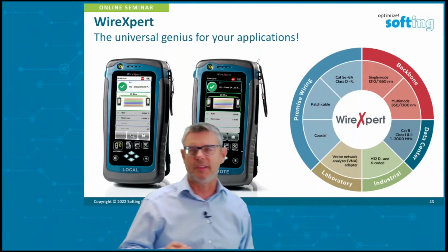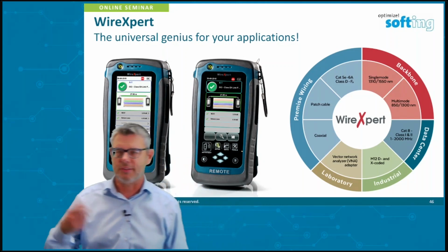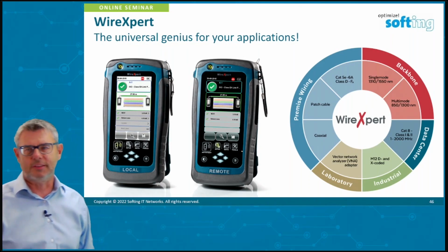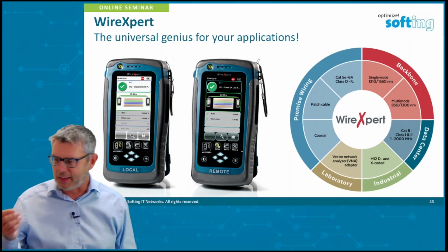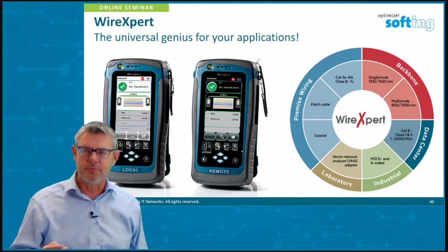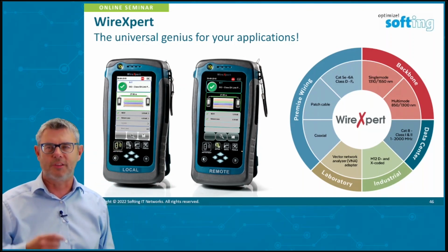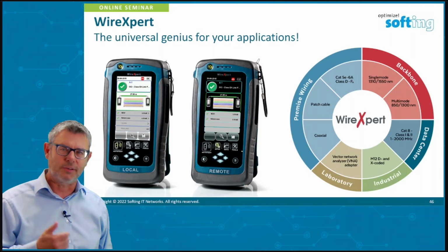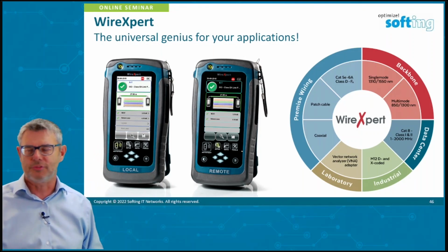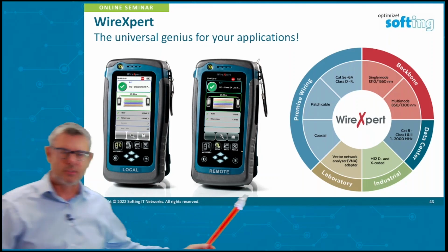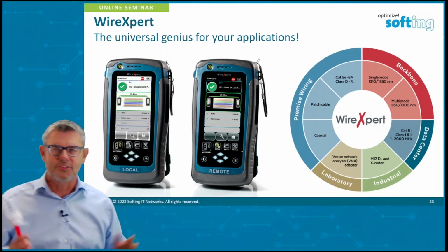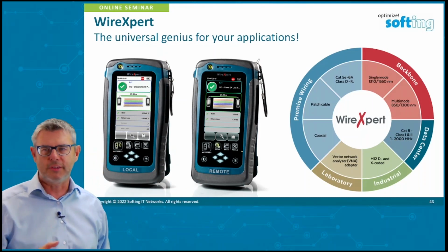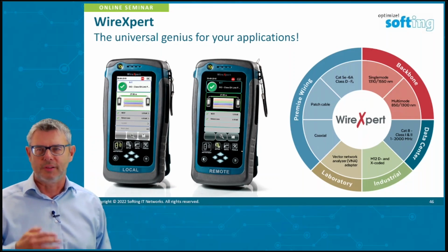With the proper fiber optic adapters, you can do testing of single mode backbone, and you can test multi-mode distribution as well. We also have an approach we call data center. Data center is going up now to this Cat8 area, going up to 2000 megahertz, and there we have special measurement adapters for the different interfaces which are used in the Cat8 world, like the Tera, the GG45, and of course the RJ45 going up to this world. Industrial, as you can see here, we also have a complete suitcase full of adapters and special test cords for the whole industrial world to cover all the different connector interfaces with the proper measurement equipment.